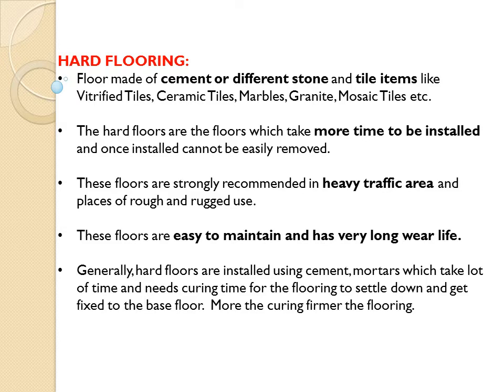The same way, coming to the next, it is easy to maintain and has a very long lifespan. Generally, hard floors are installed using cement. Between the tiles, to fix them, you use cement mortar, which again takes more time to cure. They are installed using cement mortar as it takes a very long time and also more curing time, because it needs to be properly fixed and settled, as the base has to be properly leveled and installed.